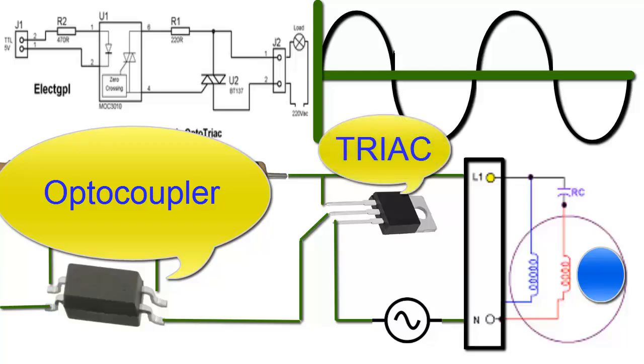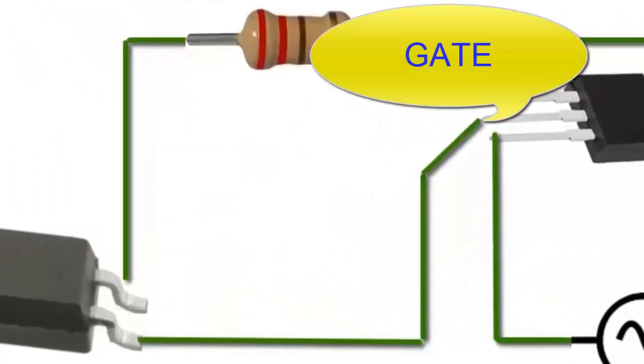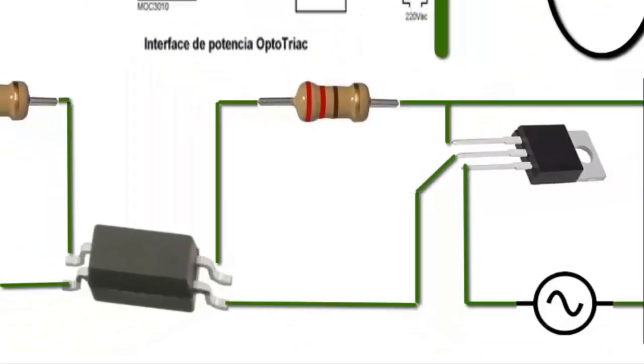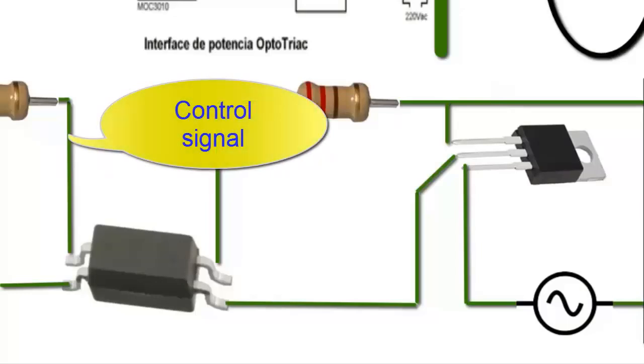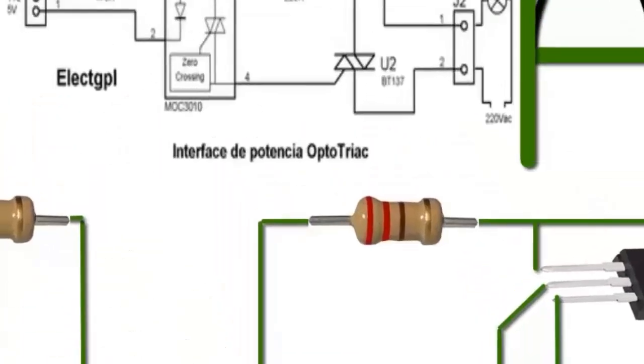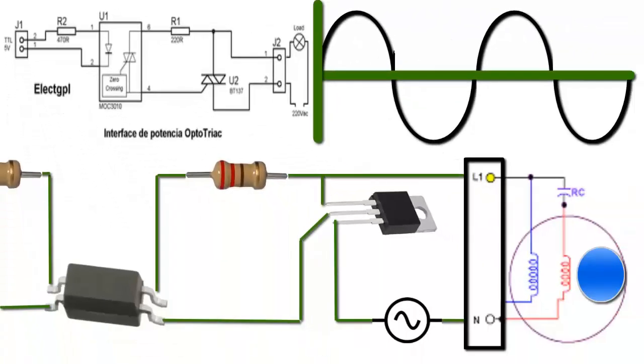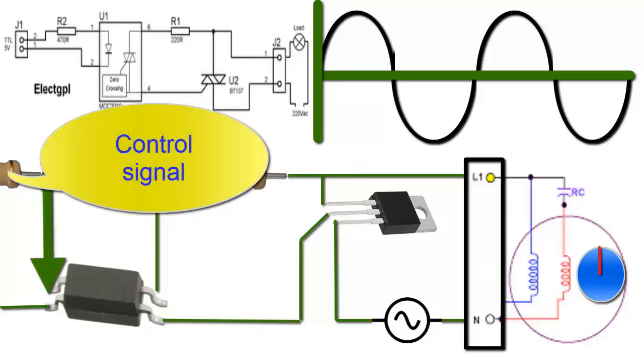The Triac, in turn, requires an optocoupler for its activation through one of its pins, called compound or gate. This optocoupler is under the influence of the main brain or controller of the electronic board, which communicates with it through one of its pins. When the controller detects the zero crossing of the voltage signal, it accurately counts the milliseconds needed to send the appropriate voltage to the optocoupler during the required activation time. The goal is to achieve a specific speed in the fan motor.